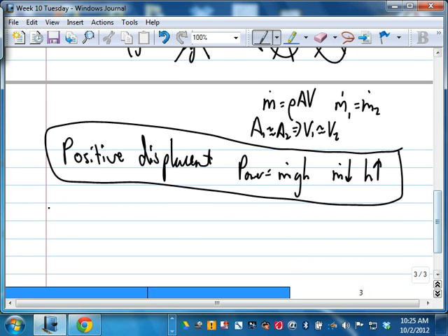Number 2, I think normally axial flow. This is actually going to turbo machinery. Turbo machinery is anything that normally rotates and is associated with fluid. We call it turbo machinery. So axial flow is the other extreme. M dot is high, the head is low.